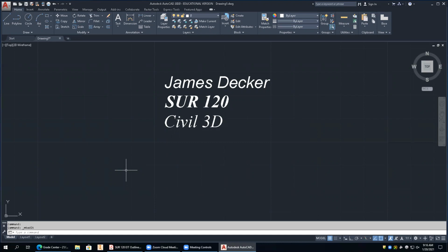So there's a really other cool thing you can do. You could paste a Word document into AutoCAD into an MText window, and it becomes an MText object. So, I mean, you can take a, well, let me do it real quick. Let me see if I can find something here real quick for you. Just show you, because this is also good to know how to use. Let me see if I can find a document.